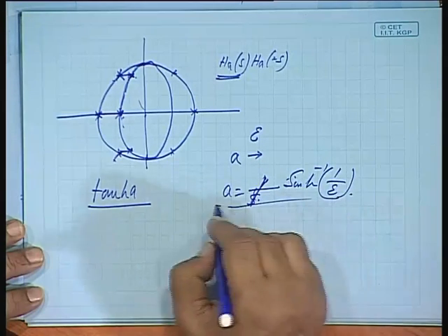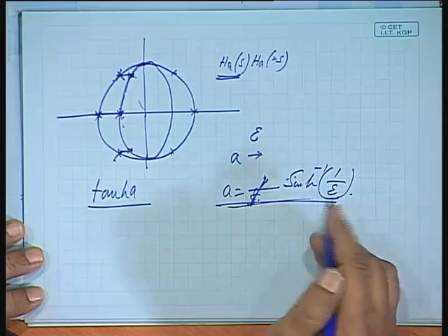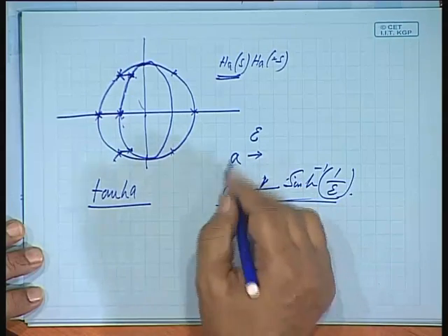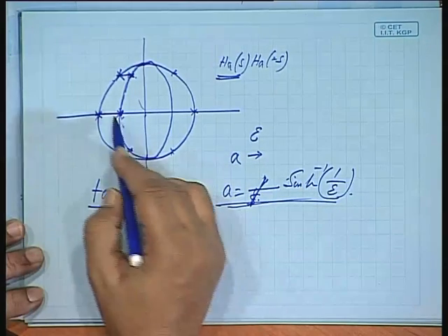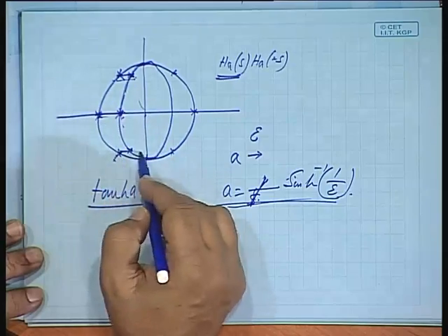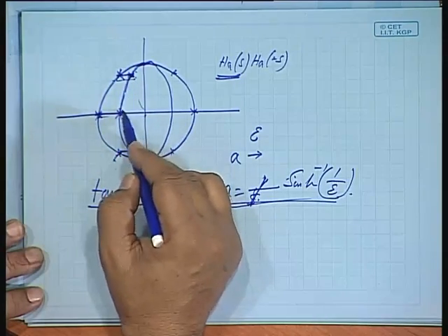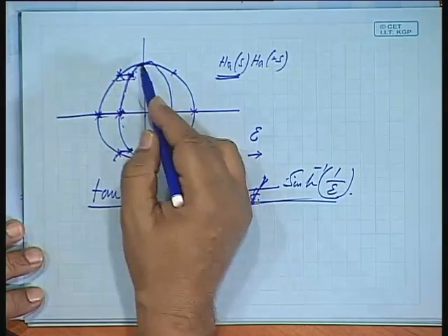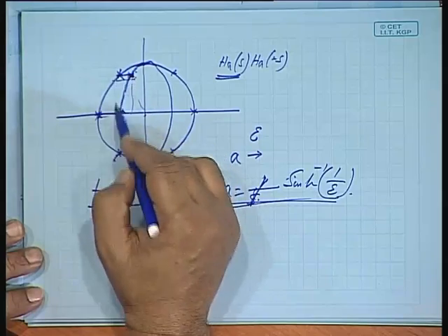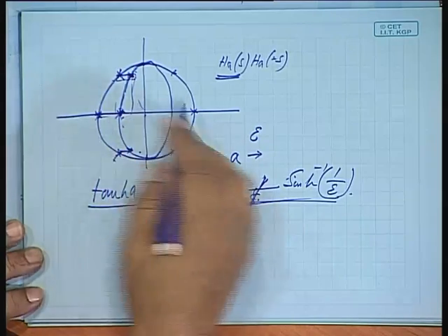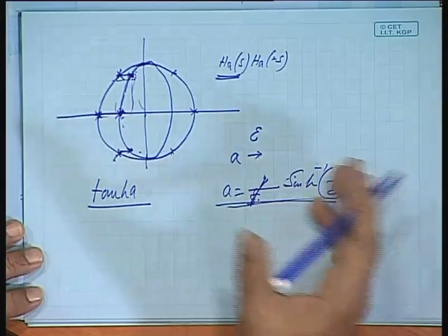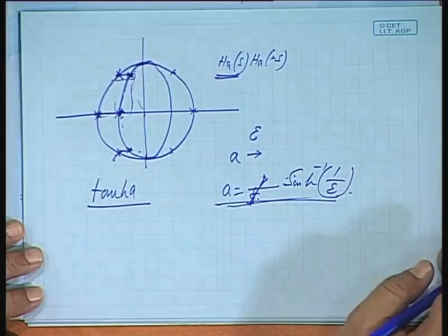There is a relationship. While designing the filter, we will get into the details of this. If you take the real part and squeeze by this factor, you get the real part of the Chebyshev filter. Imaginary parts you already know, so imaginary parts remain the same. So, you can frame the polynomial and find out the corresponding Chebyshev filter.